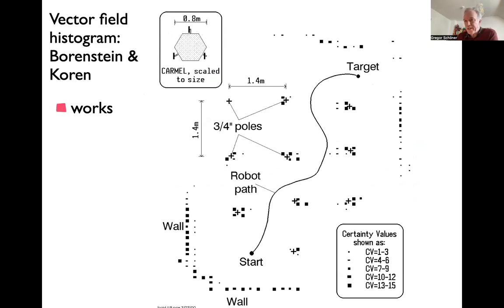It was a little vehicle, and you had a stick so that you could sense where that vehicle is driving. And so the vehicle would be finding a collision-free path on the sidewalk. Now, it was a real-world application. So I mentioned it because it sort of anticipates this problem, essentially the dynamics idea of using heading direction. And it did not have these spurious attractor states, and it was discussed at the time that it was better than some. These are actually also the guys who found the navigation function approach to solve the problem with spurious attractors in the potential field approach, and they were proposing this as a system that has less of that problem.